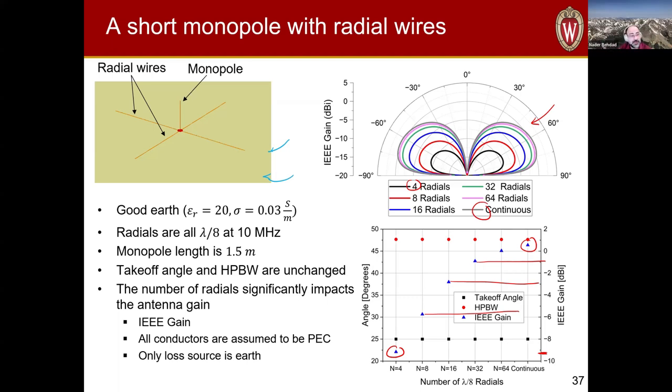I think the old NEC software also had that capability. If the ground plane is not flat in the vicinity of the antenna, then that analysis becomes much more difficult. I'm not aware of closed form formulations that are there, so this has to be done numerically, right?